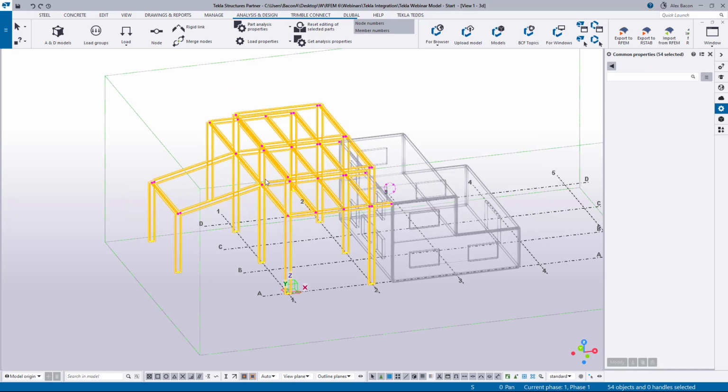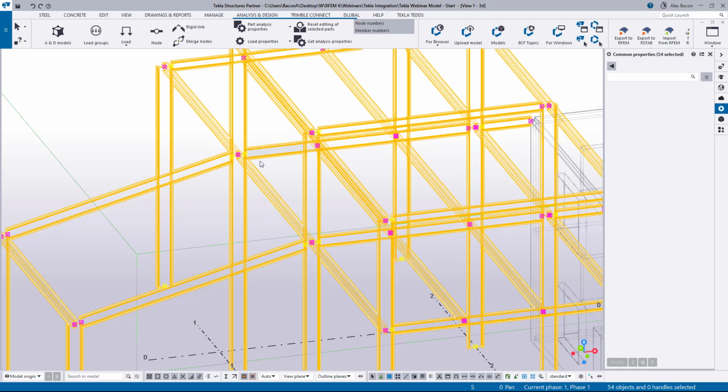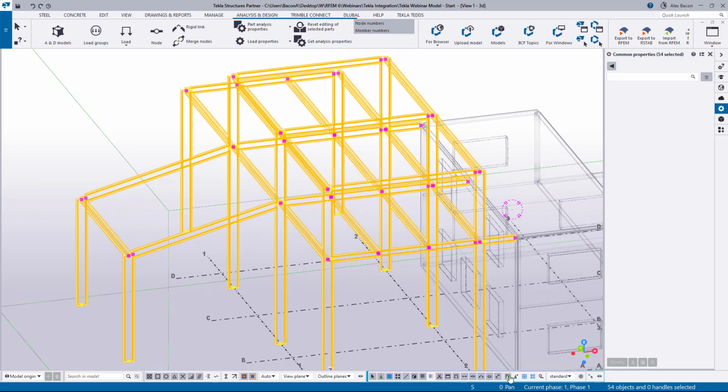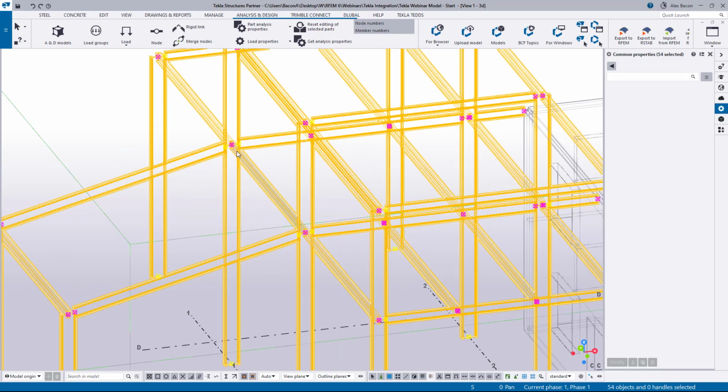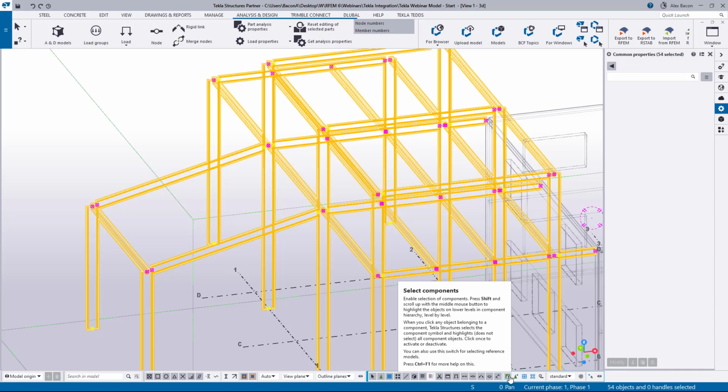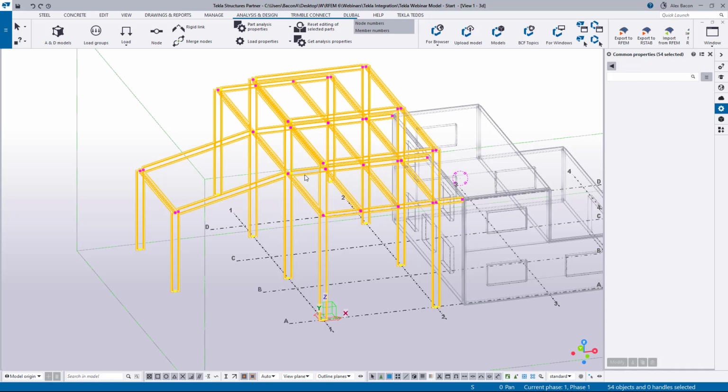One thing I would like to note is if you have any steel connections here, you can have those not be selected, because we don't want to create analytical models based on any of the steel components or steel connection components that are defined in Tekla, because then those are just profiles and they won't transfer over to RFEM correctly. So you can turn this button here off, and so you won't select those components when selecting the model that you would like to convert into an analytical one.